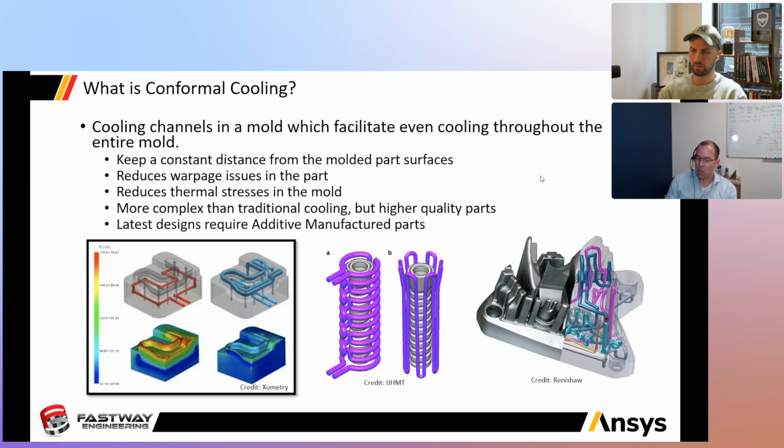So whenever we have huge stress gradients in the mold, and again, I'm not talking massive, like hundreds of degrees. I'm talking maybe 10, 20, 30, 40 degrees. But if that happens in a really, really small space, and a lot of times we have designs that have small little shutoffs or little features, and we've got a large temperature gradient in a small feature, we're talking about a lot of thermal stress.